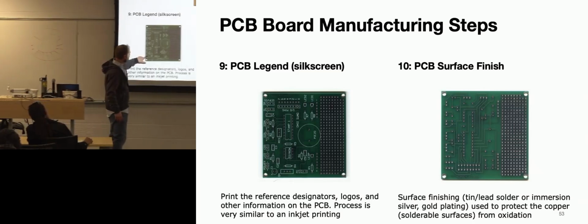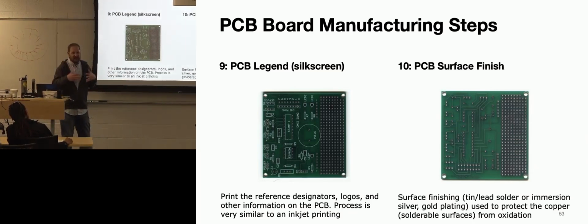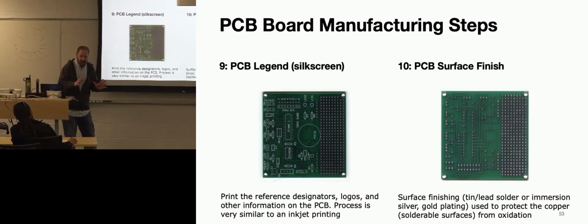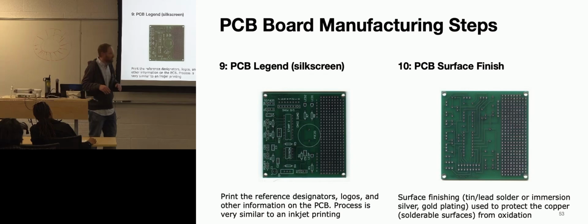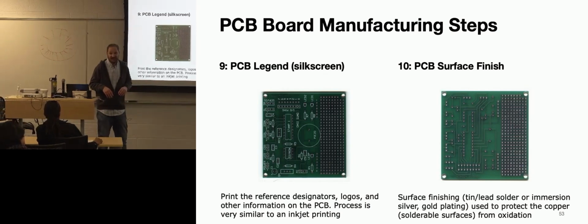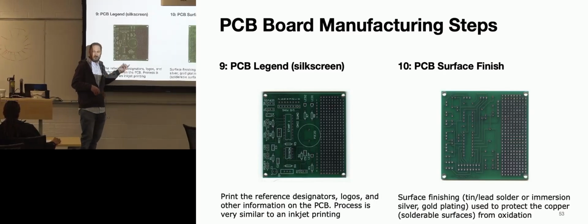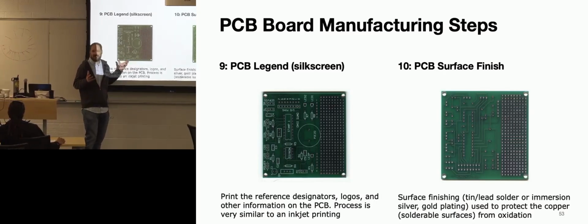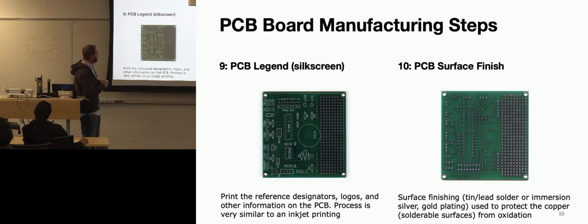Okay. Then you get a silk screen layer. The silk screen layer is for you. You're trying to help yourself in the future when you're trying to assemble it. I've certainly seen some 373 students say, oh, I just didn't get to silk screen. And then they get boards back and there's no numbers anywhere, and where do you put R2? Oh my gosh. It's an amazing decision to have that happen.